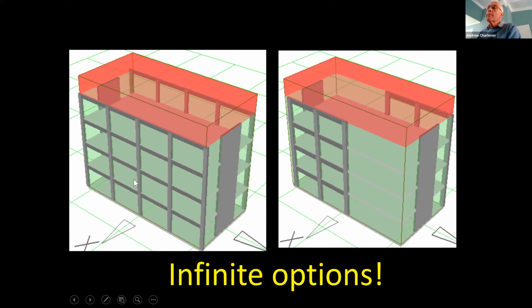You can see the frame on this side of the building, and you can see the frame on the other side over there. Now, what about in the X direction? In the X direction, these frames are useless because they're not strong in the X direction. They're only strong in the direction of the beams.